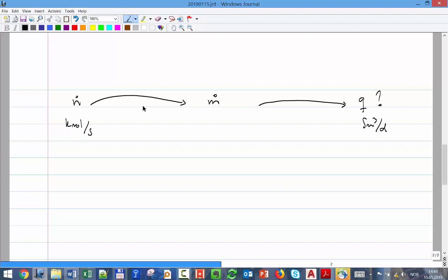I have here mass flow. How do I change from mass flow to volume flow? Density, right? You got the idea now. How do I change here? I say from kilogram, let's say per second. Okay, how do I change that to a volume? You have to say Q will be equal to mass flow divided by the density, if it's of the oil, or the density might be of the gas. Okay, whatever rate I'm calculating. Or, to avoid confusion, let's say here the density at standard conditions.